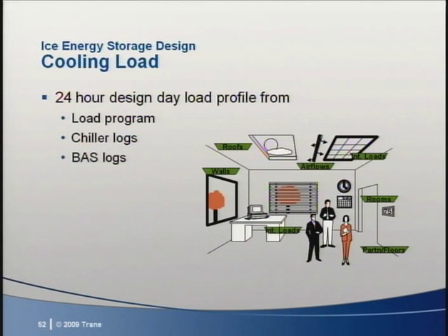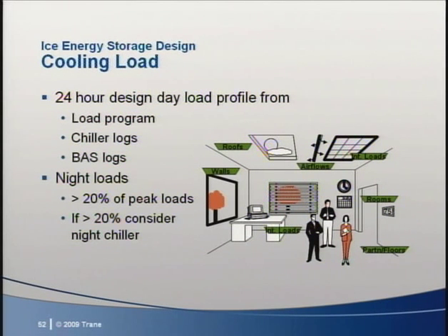Nighttime loads are an important part of an ice storage system design, and proper care must be used to include nighttime loads in the equipment selection process. A rule of thumb states that if nighttime loads are 20% or less of design peak, the cooling requirement can be met with the ice-making chiller. If the nighttime load is greater than 20% of peak, the designer should consider using a separate dedicated nighttime chiller.